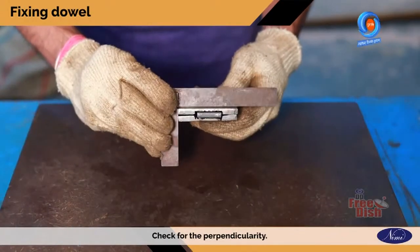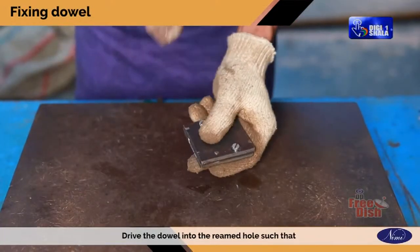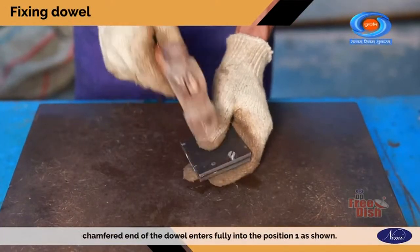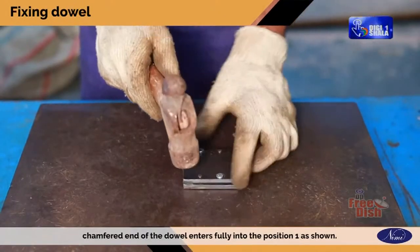Check for perpendicularity. Drive the dowel into the reamed hole such that the chamfered end of the dowel enters fully into position 1, as shown.